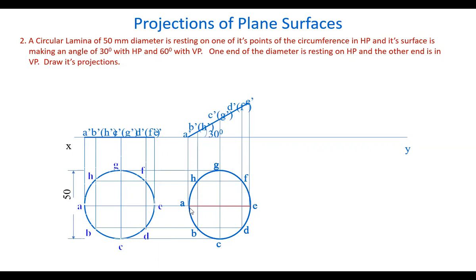So let's rotate this by 90 degrees here and take this A here and E here. This is rotated by 90 degrees and this point E comes and touches the reference line. So these two will become the reference points, and now we will draw the same top view here in this new position.